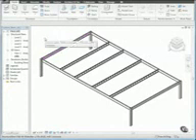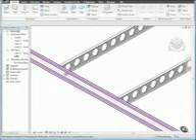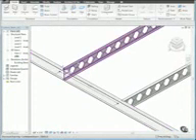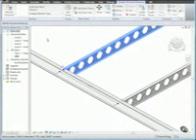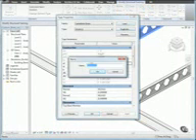Let's create a beam type based on an existing beam that shares the same properties. Zoom in on one of the castellated beams and select the beam, and from the Element Properties drop-down, click Type Properties. Then, in the Type Properties dialog, click Duplicate, and in the Name dialog, type CB 18x22 Custom, and click OK.